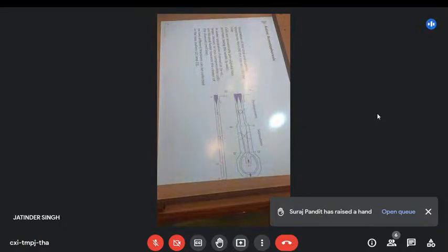the same starting point when we go to the separation points. Then we go into a wider channel where all particles line up at this focusing node, then end up in a situation where the blue particles don't experience the force to migrate towards the node based on their properties, whereas the red ones do. If the red ones are blood cells and the blue ones are bacteria, we can separate the bacteria away, collect them, and then this particular chip was used for PCR afterwards.